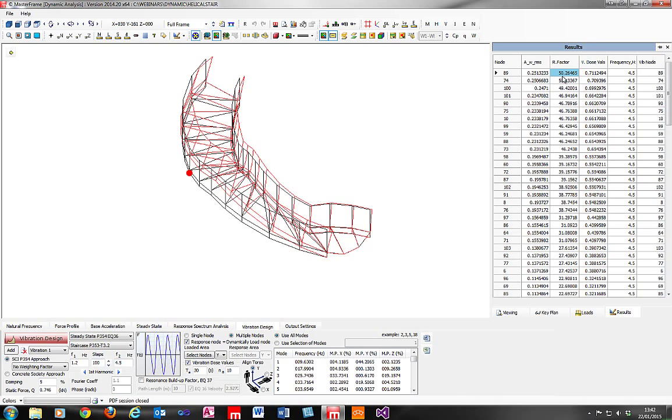I know that the P354 indicates a response factor for a stair, I'm just going to quickly look that up in the acceptability criteria, and we've got table 3.5 in the SCI P354, which talks about stairs for light use, for example offices, where you might be looking for a response factor of 32 or below. Remember, with these values, the higher they get, the worse they get. Not like natural frequency values, whereby we're looking generally for higher frequencies, but no, we're actually looking for lower response factors. We're always looking for these values to be below a certain limit.